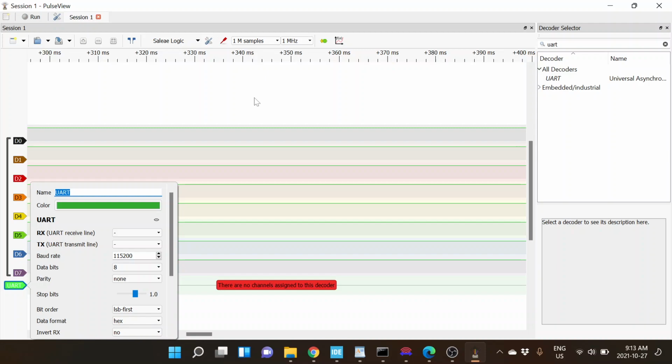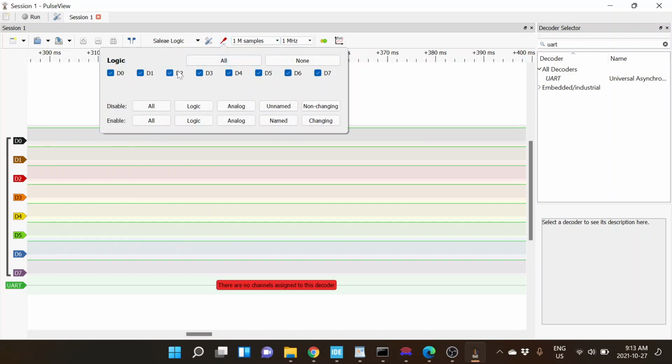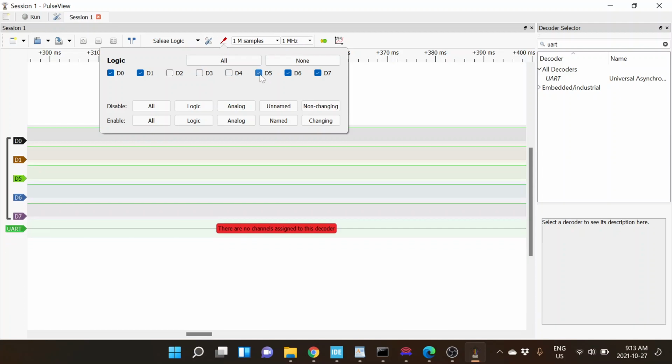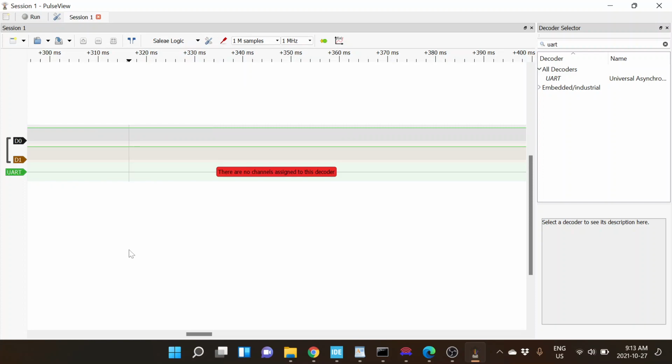The other thing is, when you go and do it, sometimes it's tricky to find out what's transmit and what's receive. Again, I was talking last day about data communications equipment, which is a modem, or data terminal equipment, which is a computer. And it's sometimes hard to tell whether the transmit pin is talking about transmissions coming into it, which is data communications equipment, or transmitting data out.